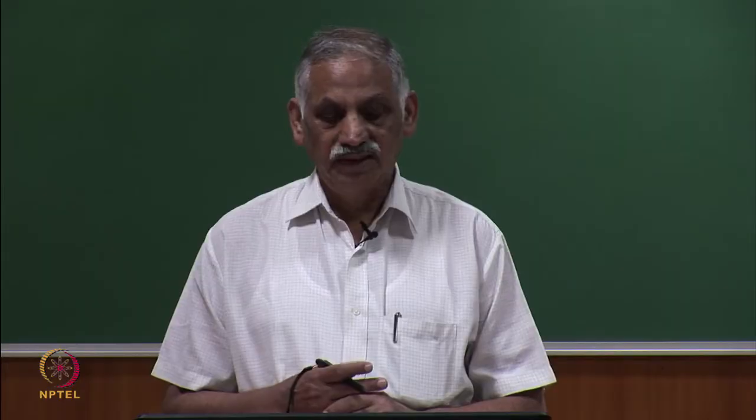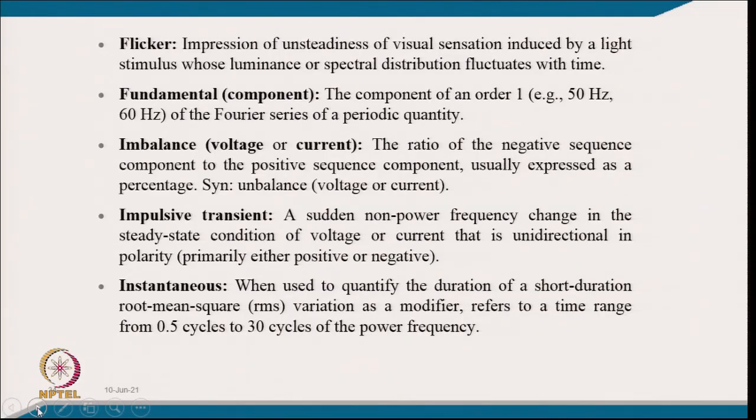So, the first is flicker: the impression of unsteadiness of visual sensation induced by a light stimulus whose luminance or spectral distribution fluctuates with time, and you see the flicker. It can be from a loose connection breaking, or you might have seen it in welding and similar loads.